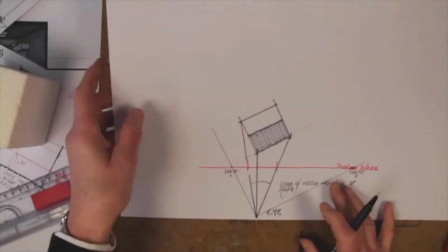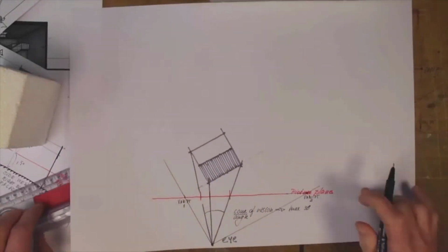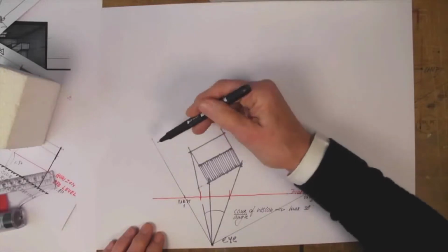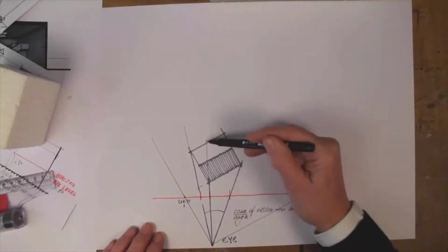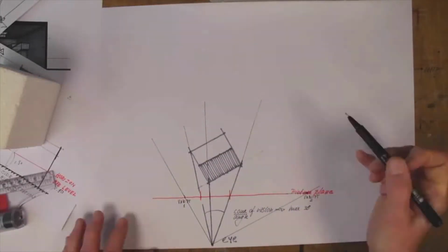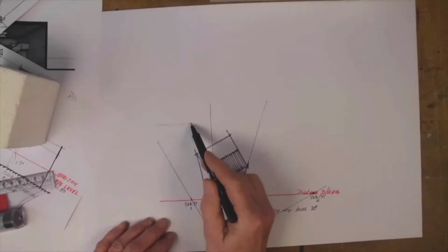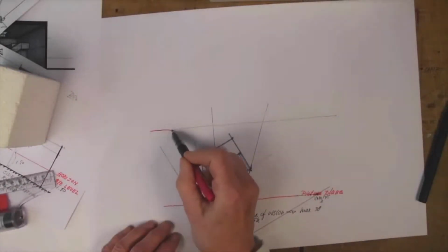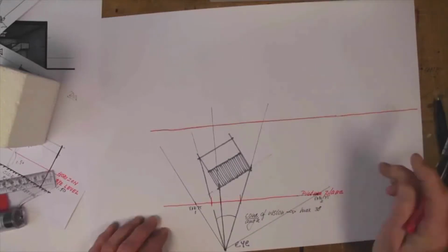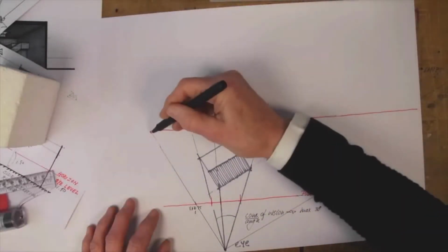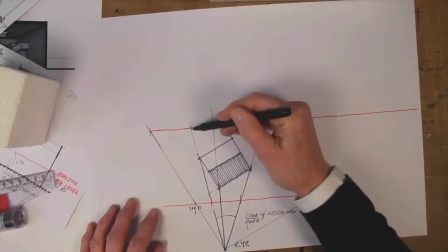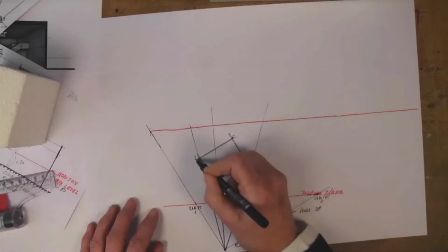Instead of putting the picture plane in between object and observer, I also can position it behind the plan. It's just a matter of relative sizes. So now I'm able to make a bigger drawing. I can place the verticals in the right positions. You can place the vanishing points and the verticals downwards or upwards, there where you want to make your drawing.